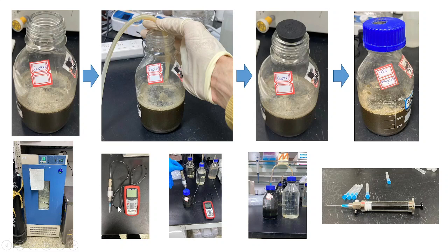And this is our pressure gauge fitted with injection needles. When you insert this injection needle in this rubber stopper, it will not affect the anaerobic conditions. It will not let the oxygen pass inside. That's why you have to use such pressure gauges with injection needles like this. It will give you the pressure reading. Every day you have to remove the biogas produced, because if the pressure keeps increasing, this bottle will blast. So you have to remove biogas every day.